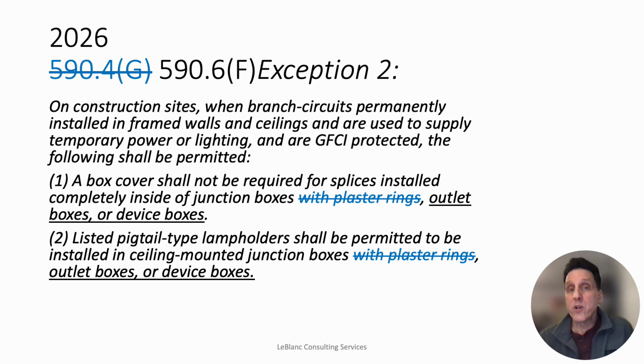And it doesn't matter what we call that box. It doesn't matter if it's a junction box, an outlet box, or a device box. We don't have to put a cover on it. We can energize it without a cover as long as it's GFCI protected and get some temporary lighting.